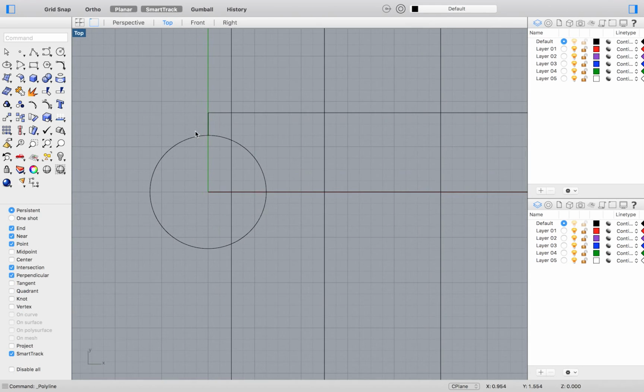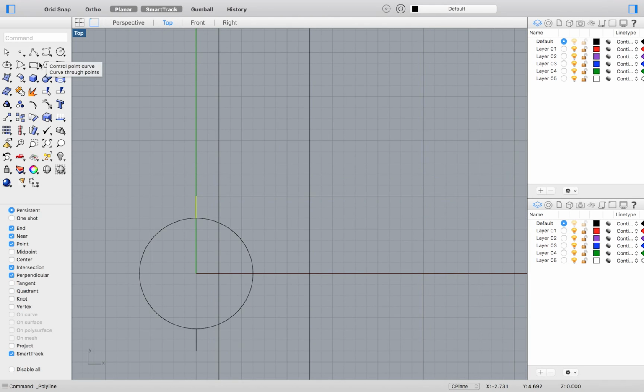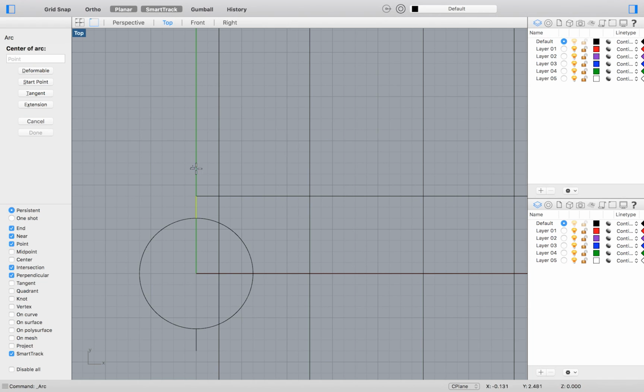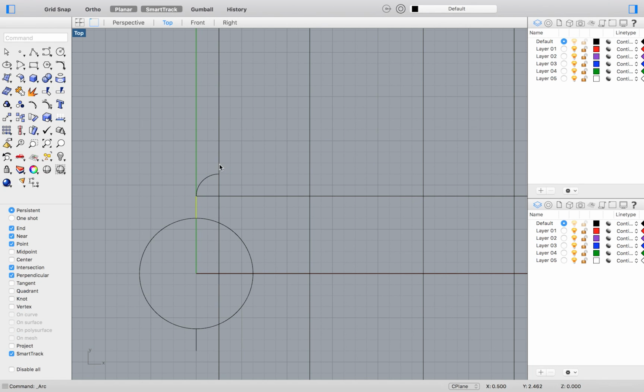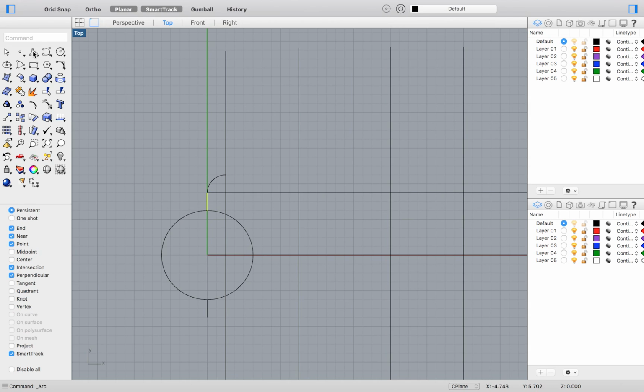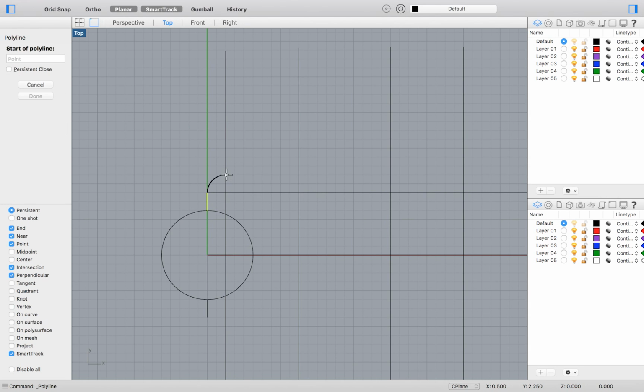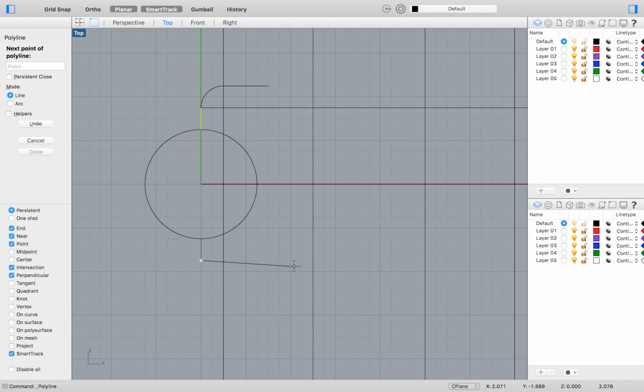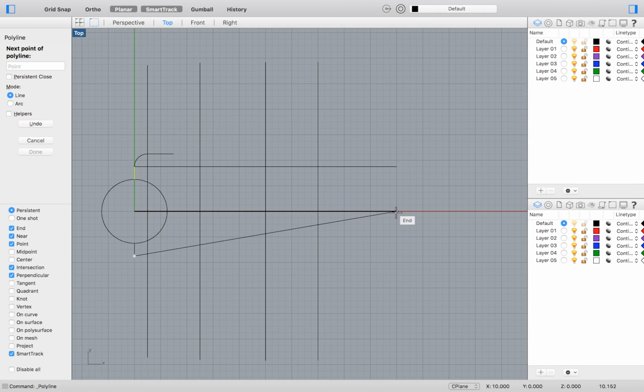Where your two most recently drawn lines intersect will be used to determine the center of your arc's radius. Click the end of your half-inch line and then hold Shift to use orthographic mode to select a perfect 90-degree angle. Now draw your top line from the end of your arc. Type 1 for the distance and hold Shift to get a perfectly horizontal line. We will perform these last three steps on the lower portion of the drawing.